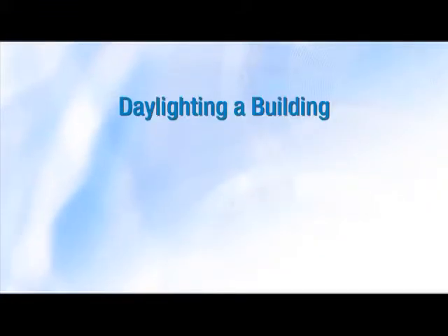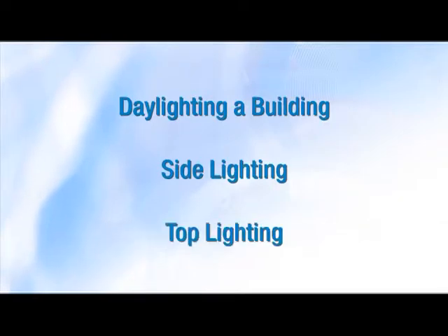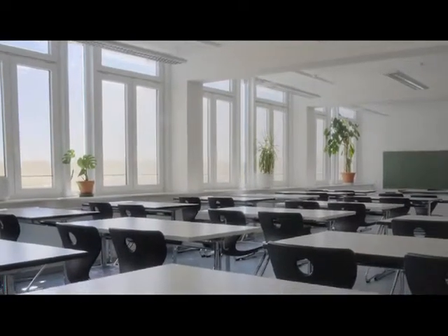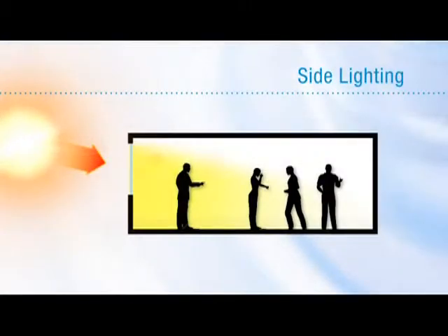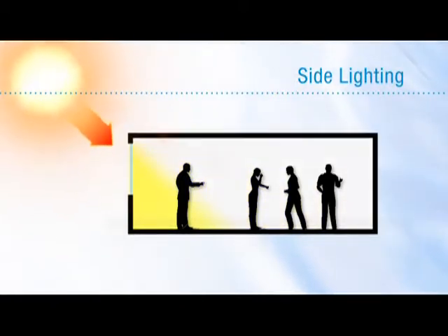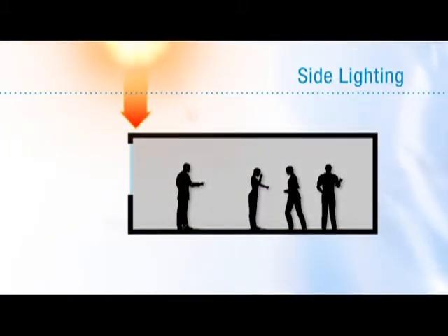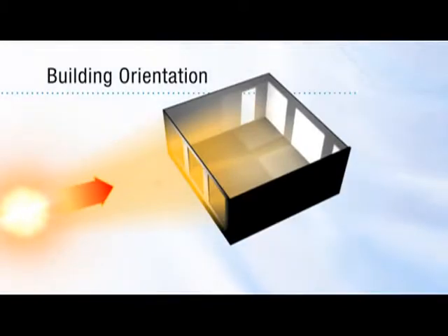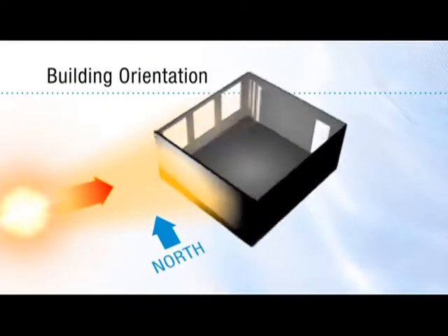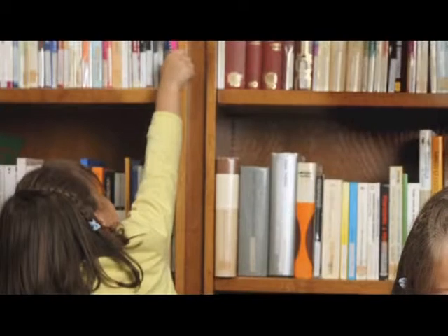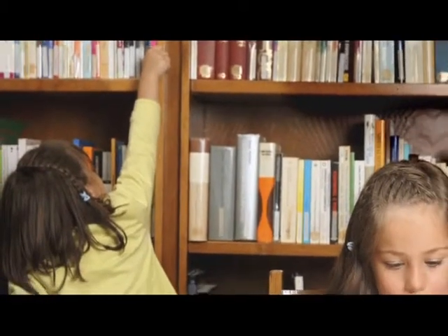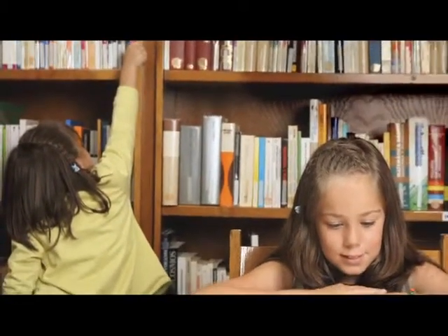There are two traditional approaches to daylighting a building: side lighting and top lighting. Side lighting is the most familiar method of daylighting, usually supplied by vertical glazing systems. It is characterized by these challenges. Daylight access from the building's perimeter creates a zone of daylight because it is often difficult to provide deep daylight penetration through typical side lighting techniques. Access to daylight is highly dependent on the orientation of the building with respect to the path of the sun and significant features of the site, such as other buildings and vegetation. This makes single design solutions for such institutional designs as schools and libraries hard to replicate.